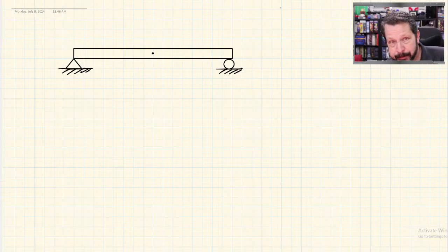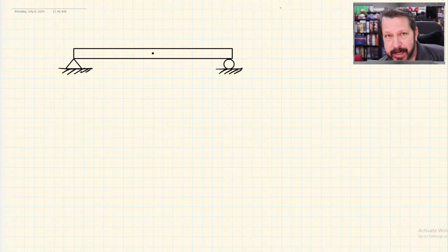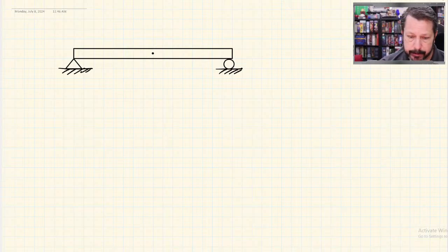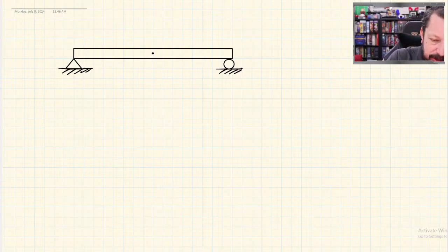We have point loads, distributed loads, and concentrated moments. I don't think we've done a beam calculation that has a concentrated external moment. We've done the concentrated internal moments; that's what we've been solving for. But I don't think we've done an external one, so that'll be a new thing for us. I'm going to draw these in our positive direction, just so the signs work out later and make things a little bit simpler.